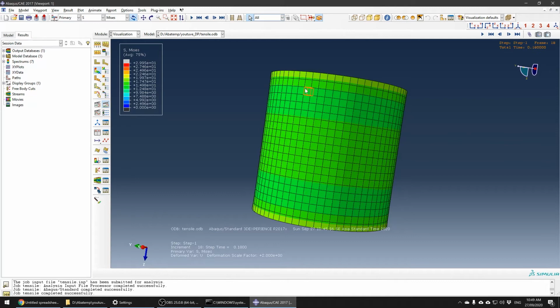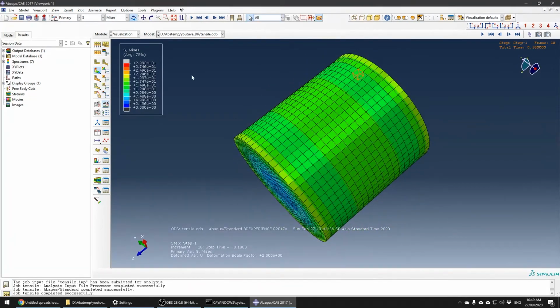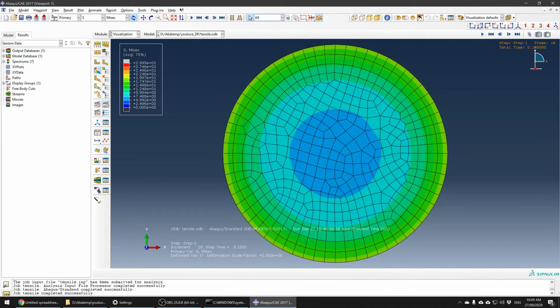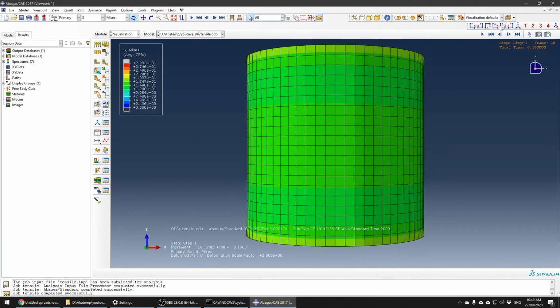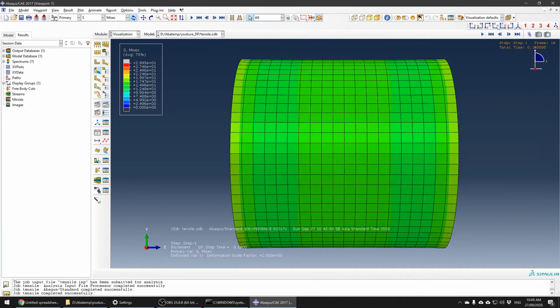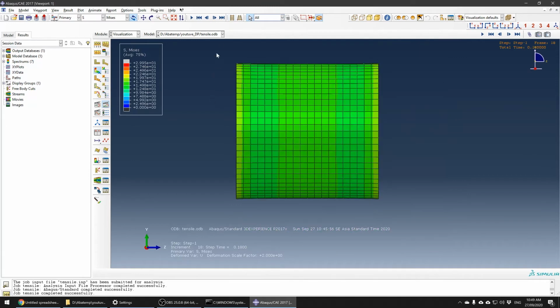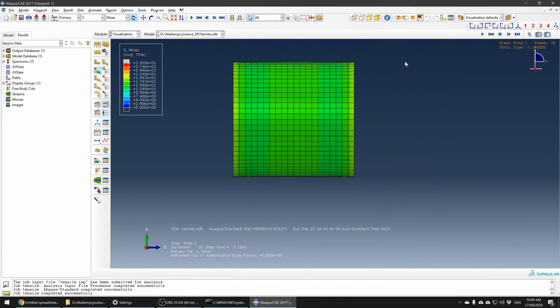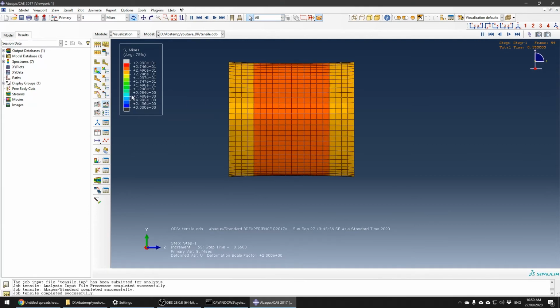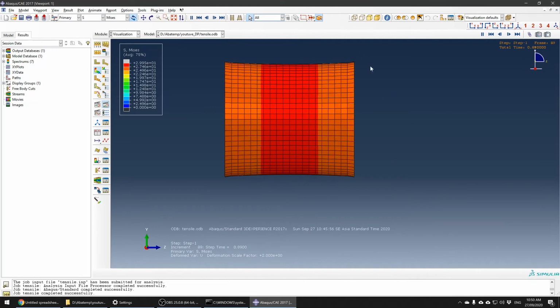Okay, so now how to post process it? For example, if I want to get the reaction force, you can just simply do it like this. Put in this YZ plane and then choose this, turn off the perspective so it's easy to choose. I'm not sure which part is being pulled and which part is the one that is resisting the pulling. So just play. Oh, so it's pulling on the left side, so we can get the reaction force here.